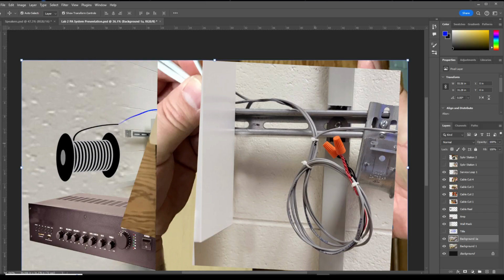So see, this is important why we need to equalize those wires first, so we could roll them onto a nice service loop, so we can come back to it, and whenever we need to service the system, we don't have to search high and low and try to guess how things were connected and what the wiring spider web anywhere in the ceiling looks like. We just go to those service loops. So much less time to troubleshoot, so much more efficient, a way of achieving something that's called serviceability.